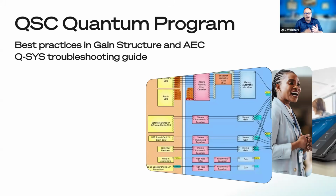If gain structure is not set right, everything downstream suffers after that. There's a saying: garbage in, garbage out. If you bring a good signal in and don't get it to the right level to go through the analog to digital converters, then you struggle with issues. And remember, there's no magic fix for a bad input. If you've got a crackly, poor quality signal coming in, there's only so much that we can do inside of the Q-SYS system.